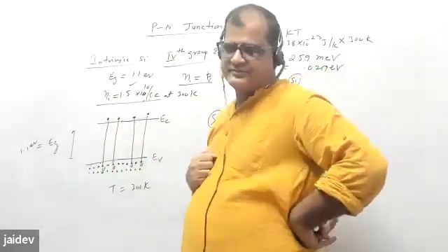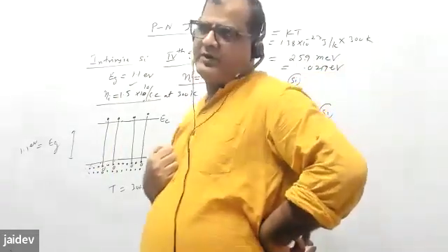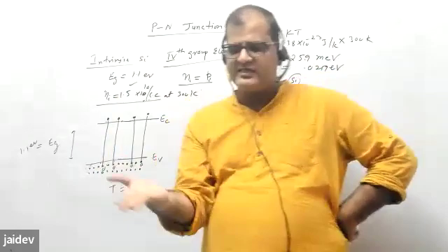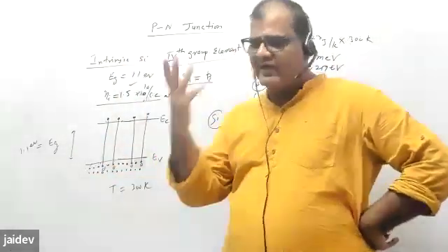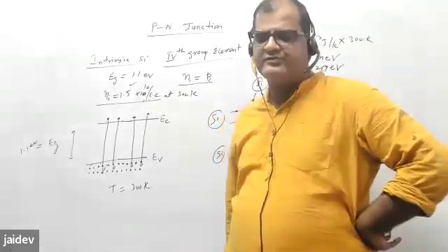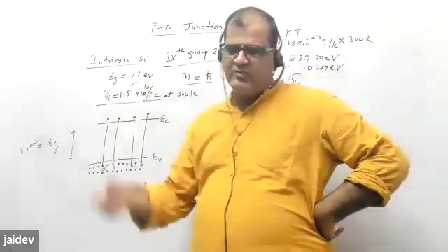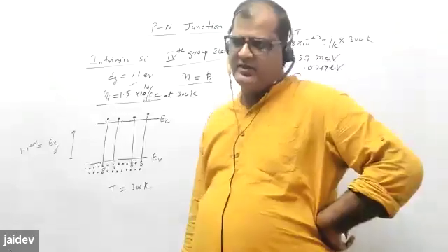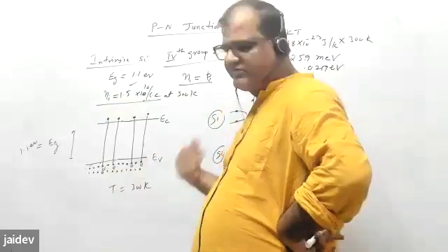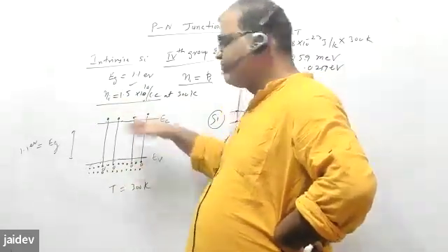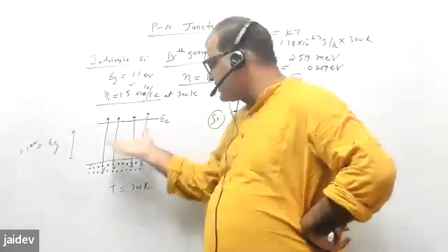Either quantum mechanically, or you can say it is thermal energy. What about the light energy? Because you are not doing the experiment in the dark, right? Whenever your crystal is there, it is kept under light. So some light photons are also falling, and light photons have very high energy, 3 to 4 electron volt, so at least 2 to 3 electron volt. UV has more energetic photons, IR also contributes heat. Because of that too, some electrons can reach here, and you have conductivity.